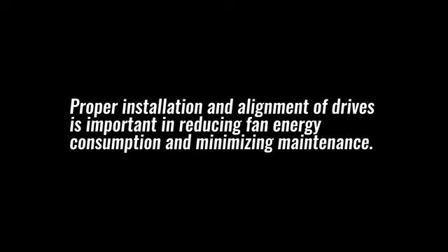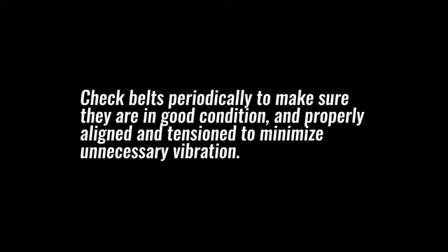To recap, for proper selection of belt drive fans, drive loss should be considered in the power consumption of the fan. Smaller motors experience a higher percentage of drive loss than do larger motors. Proper installation and alignment of drives is important in reducing fan energy consumption and minimizing maintenance. Check belts periodically to make sure they are in good condition, properly aligned, and tensioned to minimize unnecessary vibration.